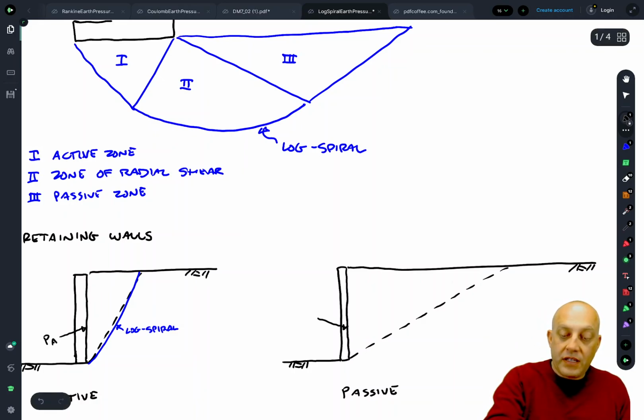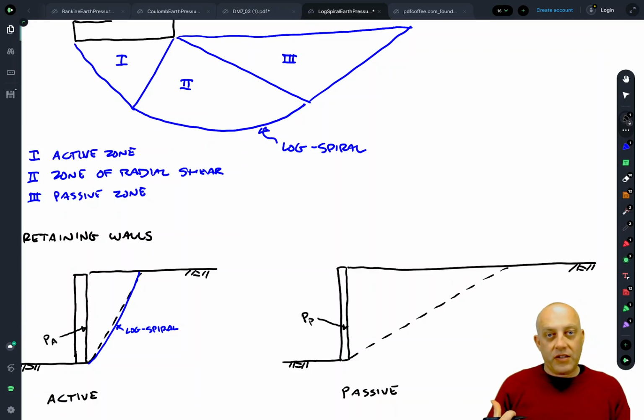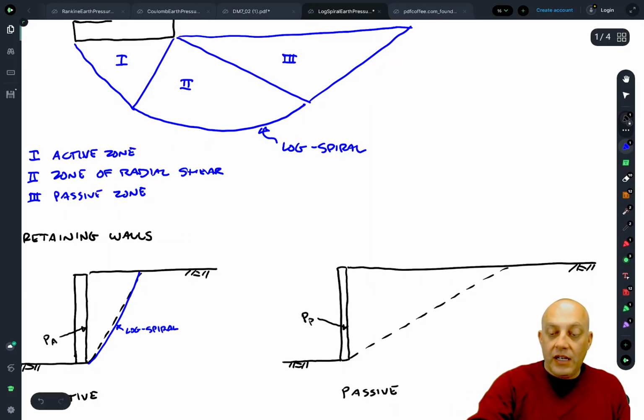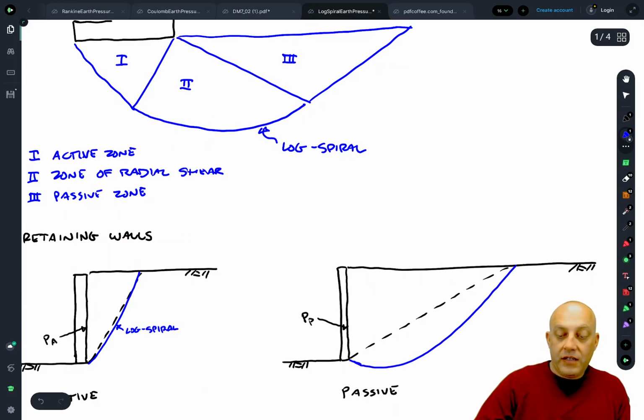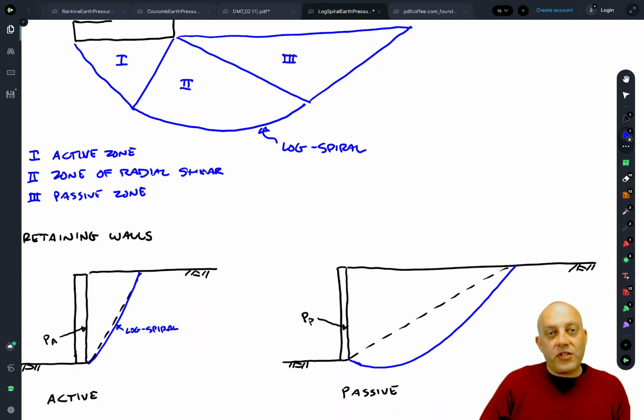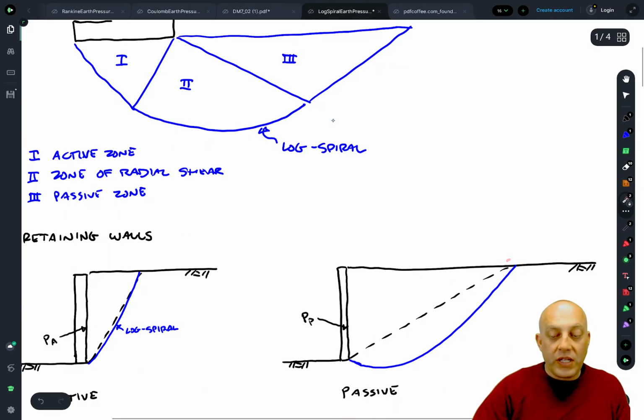We would have the wall actually pushing down on the soil, because as you push the wall into the backfill, the soil heaves up, and so therefore the interface friction is mobilized in the other direction. And as a result, the launch angle here is downward, right? So as this one was upward, this one is downward, and it follows a log spiral and maybe comes up like that. And this is just schematic. I'm not saying that they end necessarily at close to the same point there.